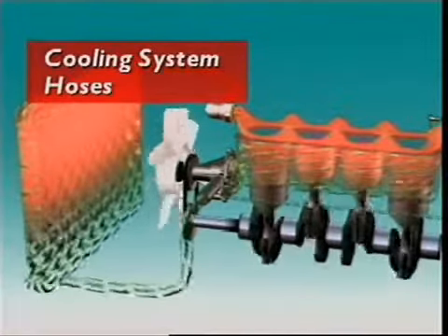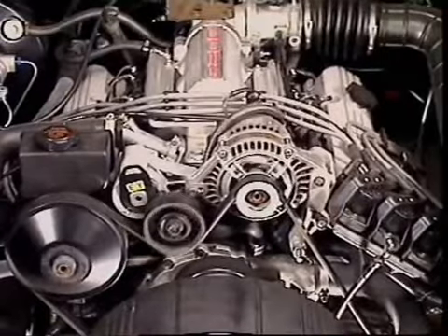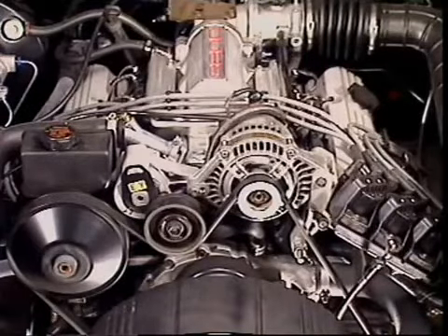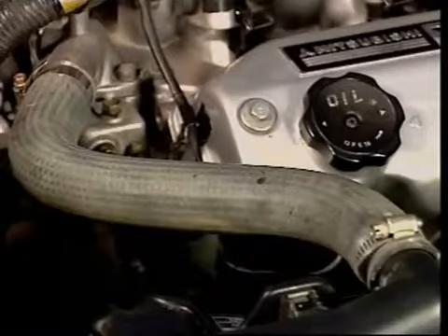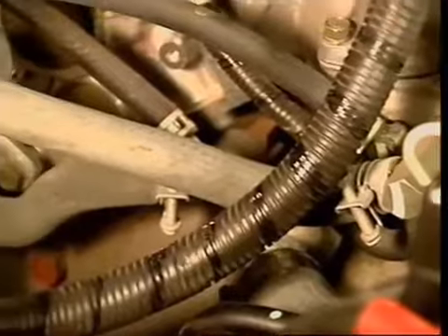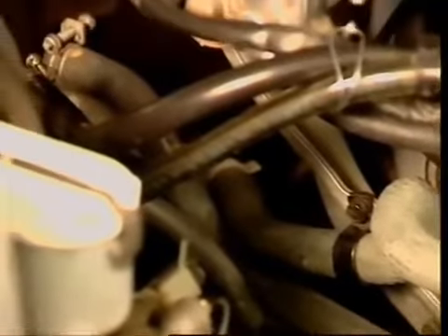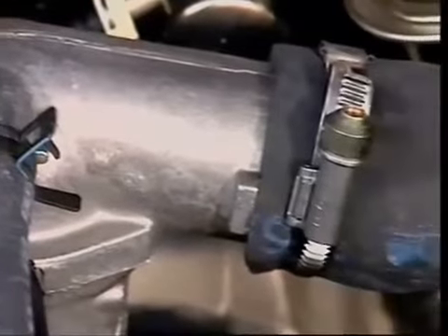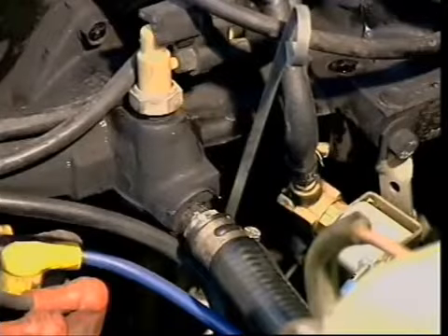Coolant is transferred throughout the cooling system by hoses. Most vehicles have the engine mounted on flexible mountings to reduce noise and vibration. Since the radiator is mounted to the vehicle body, flexible hoses are needed. Coolant is also carried to the heating system, which is usually inside the cabin of the vehicle. Coolant hoses vary in diameter depending on the volume of coolant that passes through them. Heater hoses carry a smaller volume.